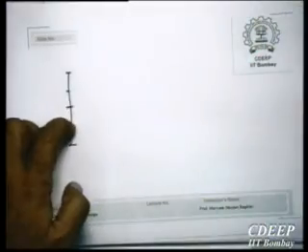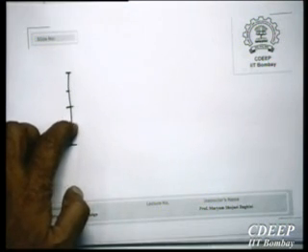The other possibility is that I could raise my reference by half the value. So I had the reference at quarter here, the new reference that I have introduced now is the quarter value. Right? So I could raise the value of the reference by half the bit and then do the comparison. Right? Both of them are okay.